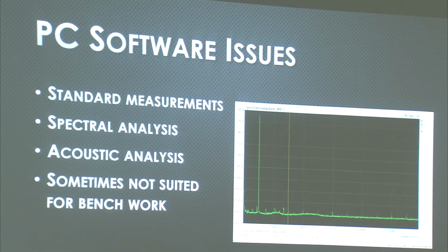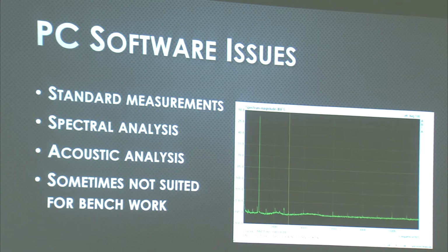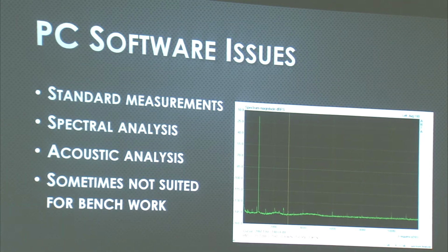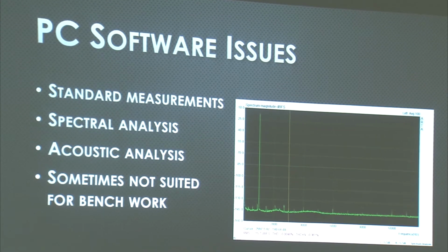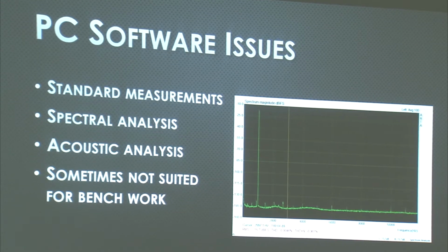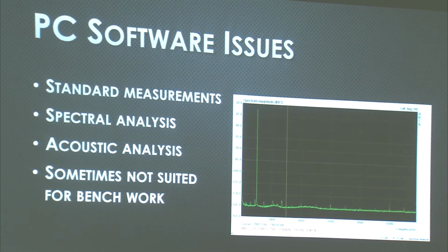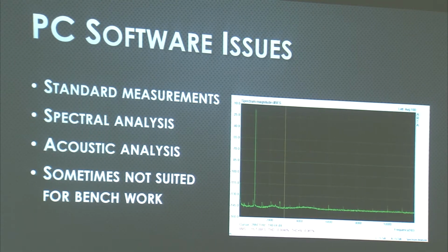With the software you can get today, you can do all the standard measurements just by pushing a button, and you can get a lot of information. The chart there is a spectrum of basically an oscillator. As you can see, the distortion is very low. You can see what it's made up of. There are all these little spikes down there. Those are either harmonics or spurious signals. And after a while, you'll be able to say, okay, those are harmonics. That is a spurious signal, and it's probably coming from, say, a USB interface, or there's this other power supply thing, or something that has to be fixed. It's very useful for understanding what's going on inside of the box.